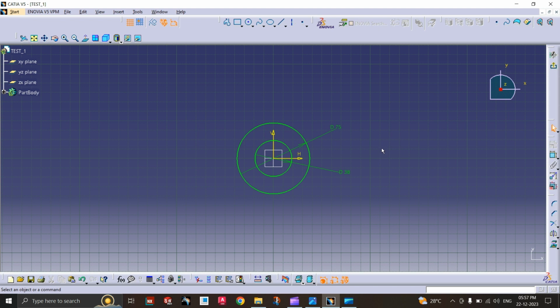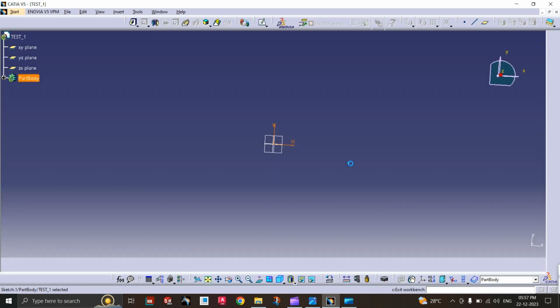So guys, whenever we create a sketch in this software, check whether our sketch is completely constrained or not. We have a sketch solving status here. We'll click on this, and we can see that our sketch is completely constrained. This is important while making a 3D part, because a constrained sketch won't change unexpectedly. So this sketch is constrained, so we will exit.